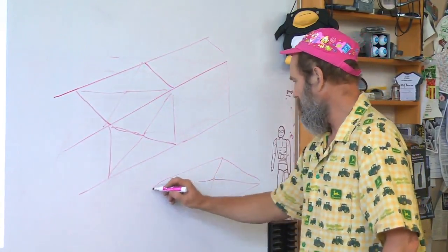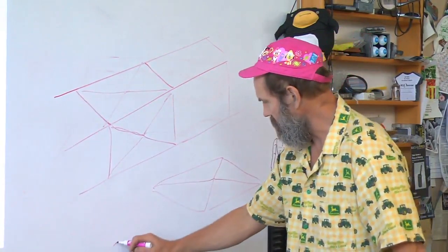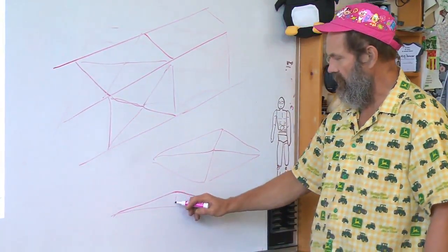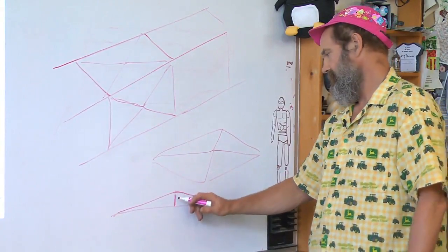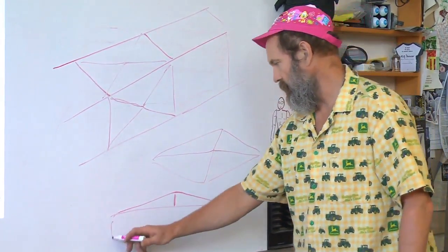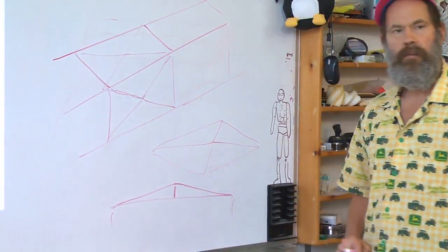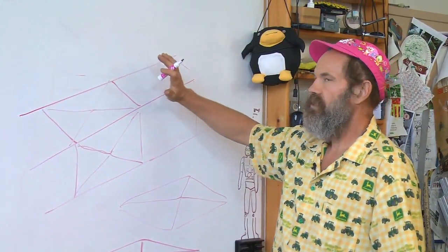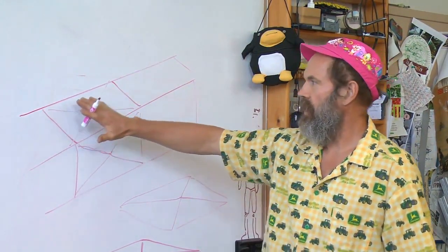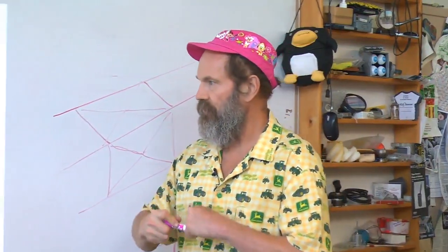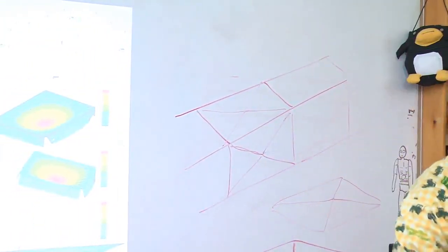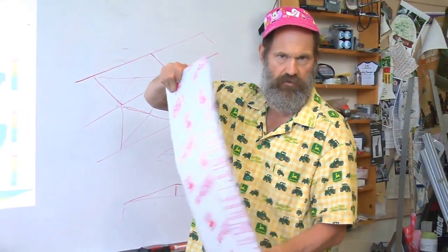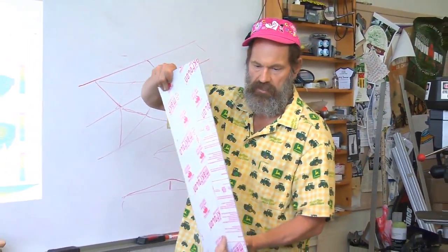It's a pyramid, so if I do a cross section, I'll see it goes up and down. And it's ever so subtle. It may only be on the order of a centimeter or less over a range of 100 centimeters. But that's enough to make these plates stable so they're not a taut diaphragm, because a taut diaphragm will oscillate between the two modes, this mode shape and this mode shape, because it's neutrally stable.